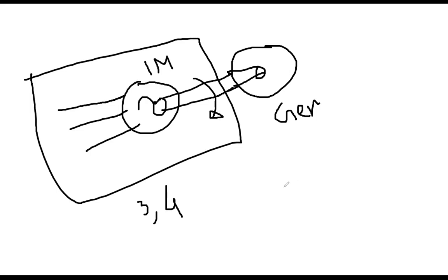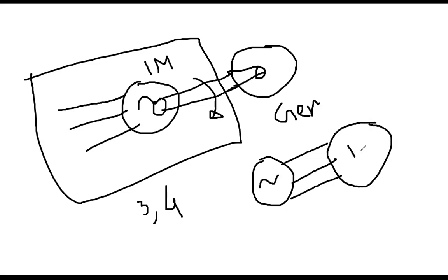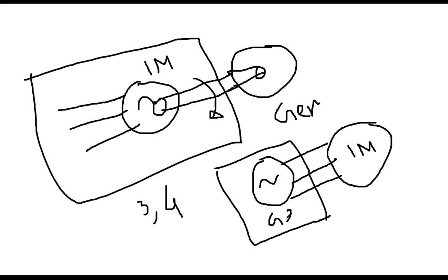The same thing in lab number 5 and lab number 6, the day you will be using the generator, because the generator will produce voltage. Therefore, what will you do with the produced voltage? Then run a motor, for example, the induction motor. Therefore, for lab number 5 and 6, although your goal is to do the generator experiment, a motor will be connected. And if you change the speed of the motor, then the terminal voltage will change. So that's why you are using the motor, meaning that the induction motor will be the load for that experiment. That's why, don't be confused.